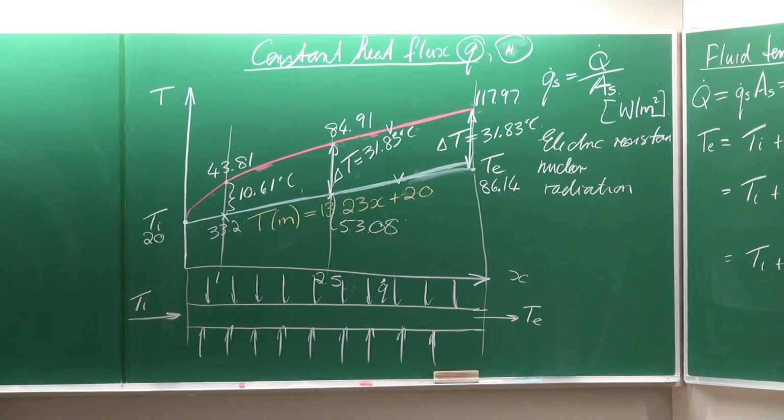In this chapter, specifically in the laminar flow, we're going to assume the flow is what we call forced convection only. So there's no secondary flow. It is just forced convection, and then this is valid. The secondary flow, in terms of its development, hasn't been fully described yet in terms of easy equations. So to walk the whole path, we do this chapter and assume the flow is forced convection only. In the next chapter, we're going to incorporate mixed convection, and it is only after that that you have all the tools where you can take secondary flow into consideration. So for this, we assume it is forced convection only.